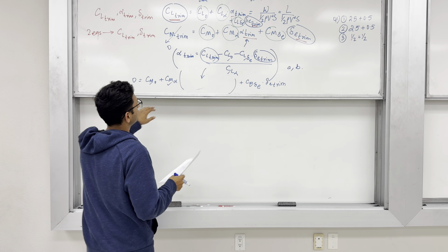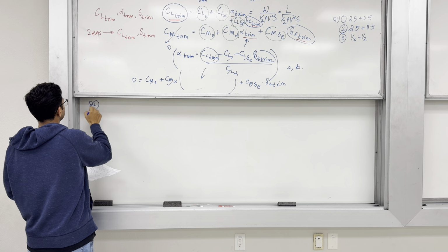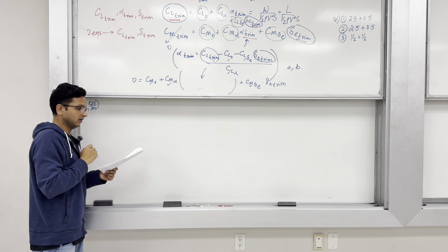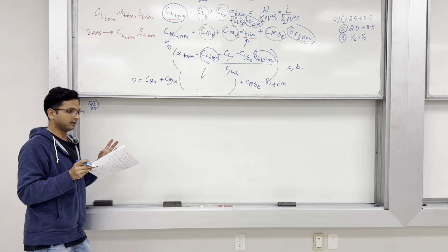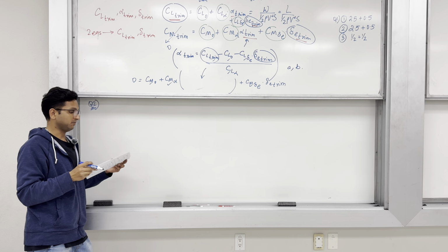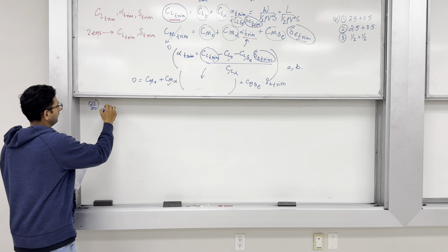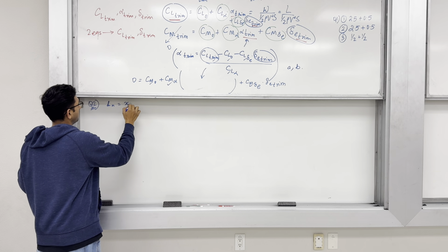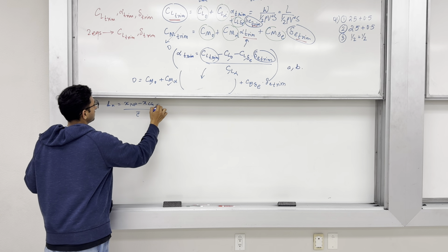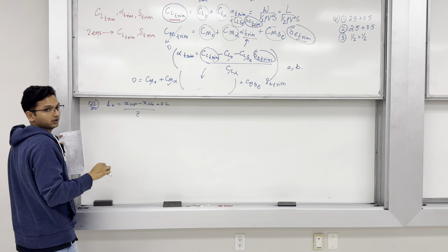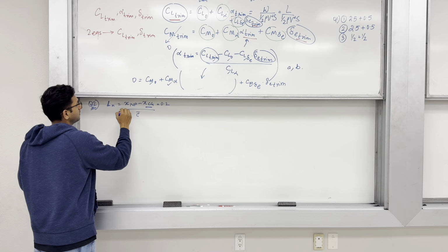So, again no need to read all of the information that is given at the start of the question. Our target here is to determine the center of gravity position for 20% static margin. So, again when you start with center of gravity, you have to start with the static margin. So, you get x neutral point minus x C g divided by C bar, and this has to be 0.2, right.